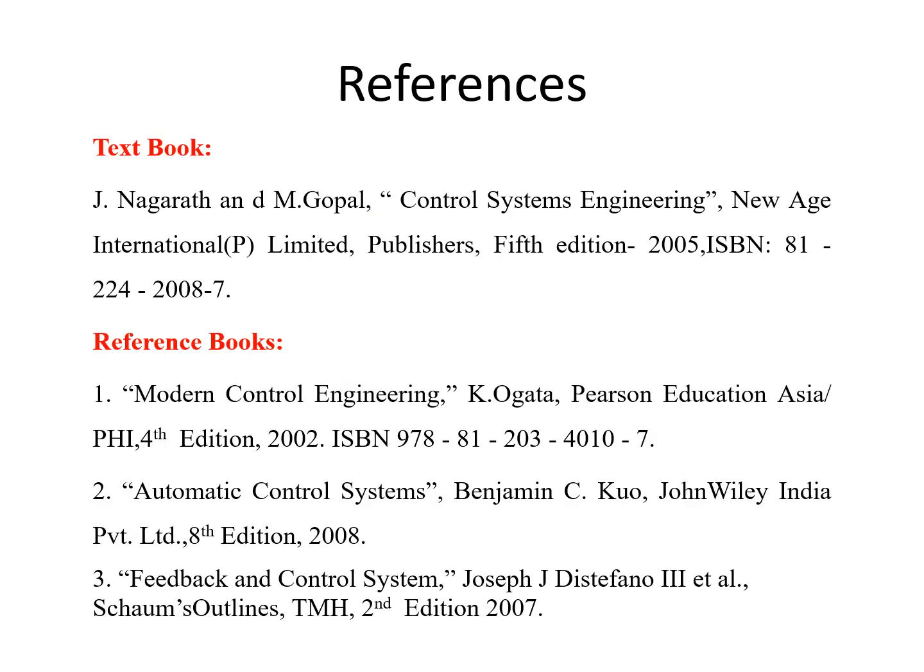So I'm ending my session for today. Today we have discussed steady state errors and error constants, and we have seen how we can evaluate the steady state error and error constant value for different types of systems. And you know that we are able to analyze the different types of systems based on the number of poles that we have at the origin.